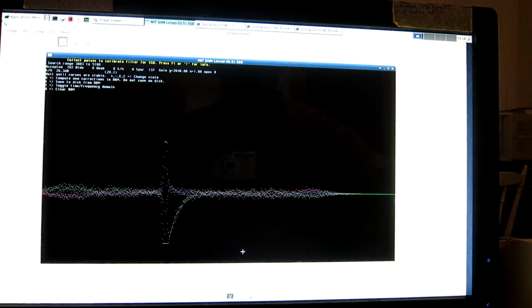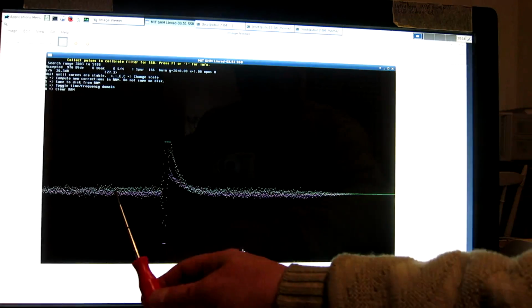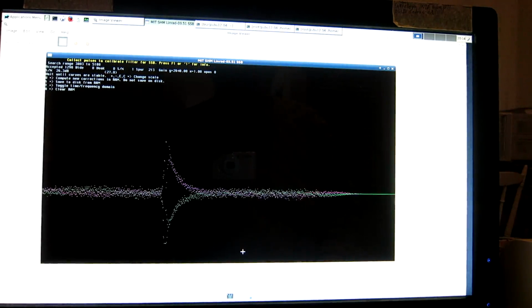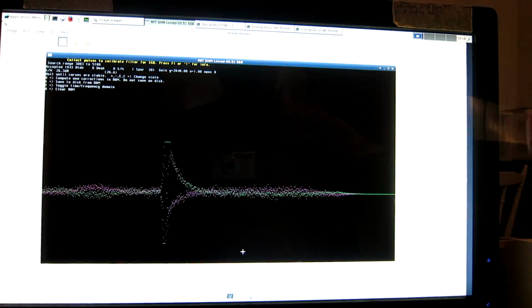And you can see the effect of the 50 Hertz from the sound card traveling slowly. That will average out in the average of transforms. But it's necessary to not trigger the pulse source on the mains frequency, because if one did that, the interference would stay at the same position relative to the pulse, and that would generate incorrect calibration.